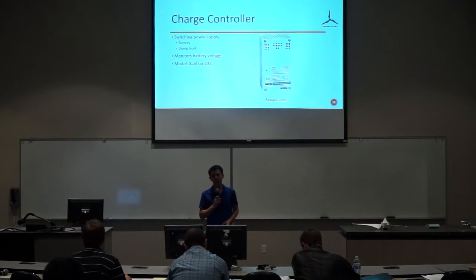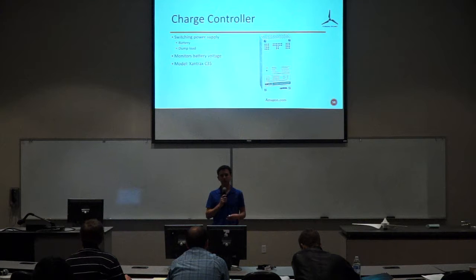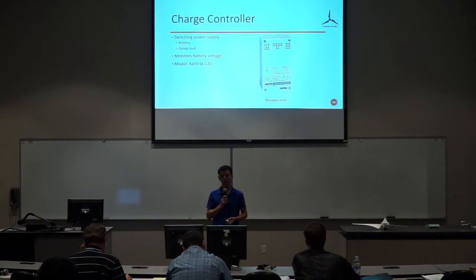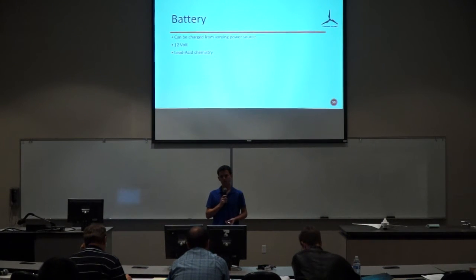Our charge controller is essentially a switching power supply that will charge the battery, and once the battery is fully charged, it will divert the power to a dump load, and it monitors the battery voltage to select between the two sources. The model that we've selected is a Xantrex C35 charge controller. It's commonly used for wind turbines and is a good choice for our application.